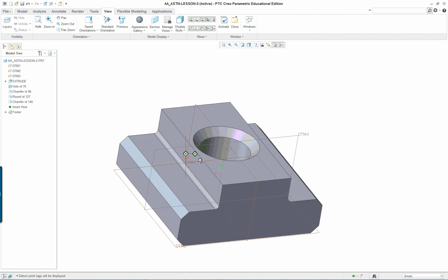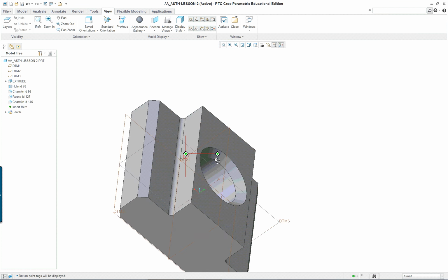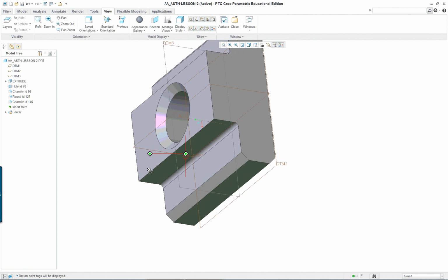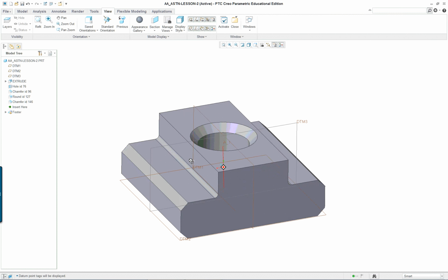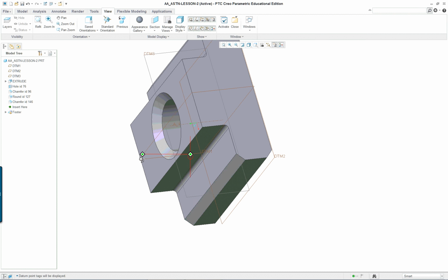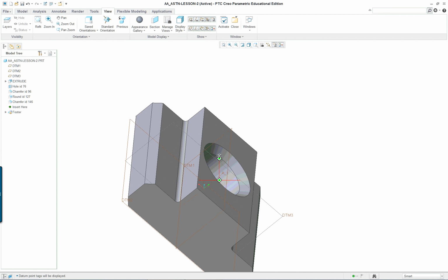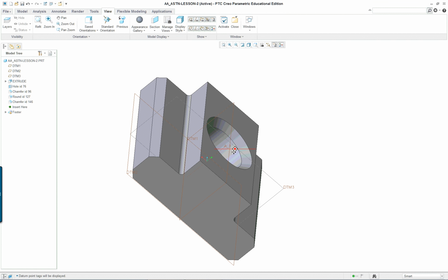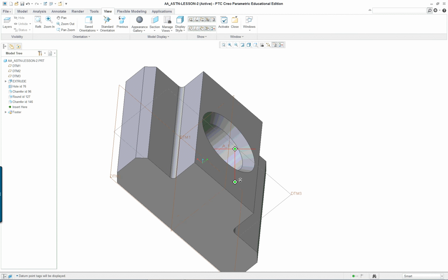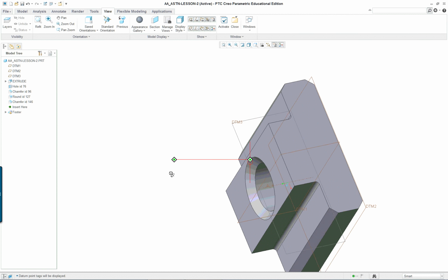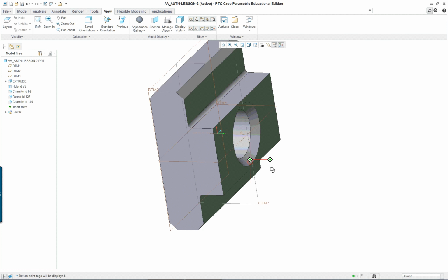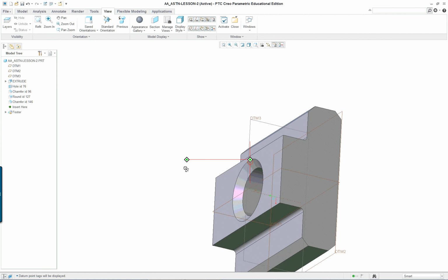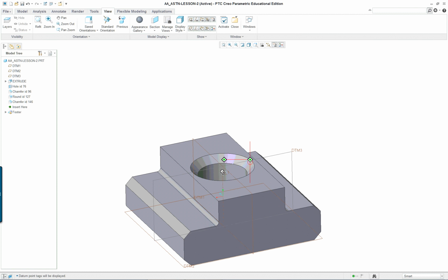But what if you just hold the control key down and then you go horizontally? Well, you can rotate about an axis point. So there are times you might want to do that. If you hold down your control key and you go up and down, or your Shift key, that's zoom, but if you go this way, it's rotate. So this is Control middle mouse button, but moving your cursor horizontally.